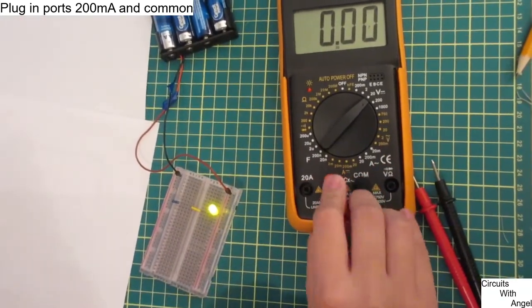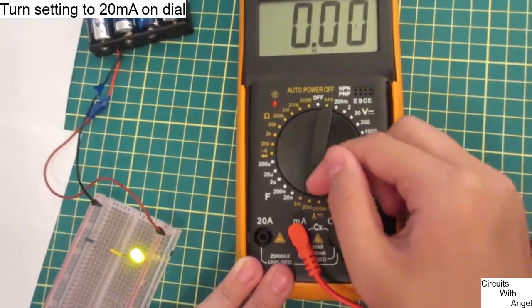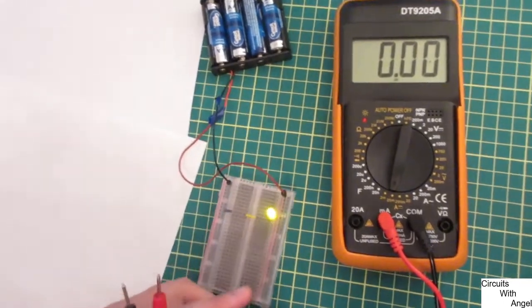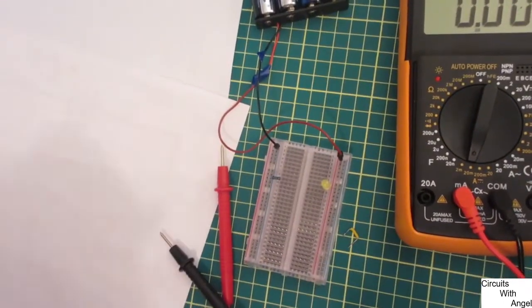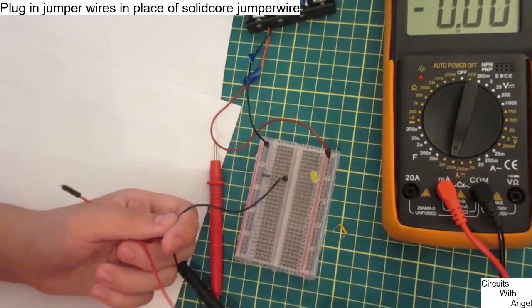We plug the multimeter to 200 milliamps and common port. It's going to stay like that for the rest of the video, so you might want to keep that there. We turn the dial to 20 milliamps since there shouldn't be much current. We're going to become the jump wire using our multimeter as the connection. We take out the jump wire and we replace it with two of our own jump wires, linking the components together.